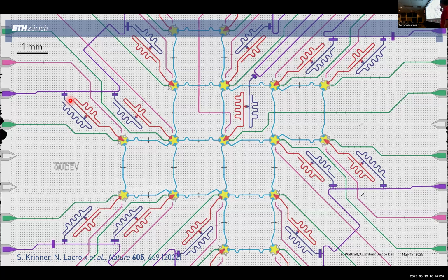And the frequency selectivity comes from the fact that every qubit has a readout resonator at a slightly different frequency, so that you can frequency division multiplex this readout. Essentially you can send a pulse into this feed line that is in some sense monochromatic, where you have a pulse that targets every individual readout resonator, and the width of that pulse in the spectrum needs to be smaller than the separation in frequency space of these different readout resonators from each other.